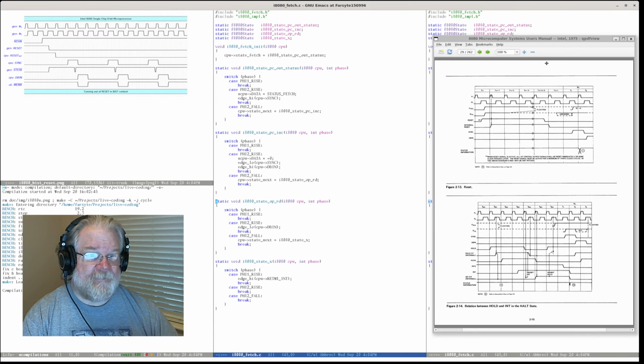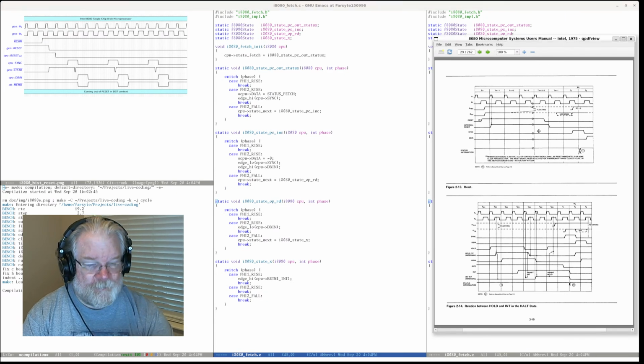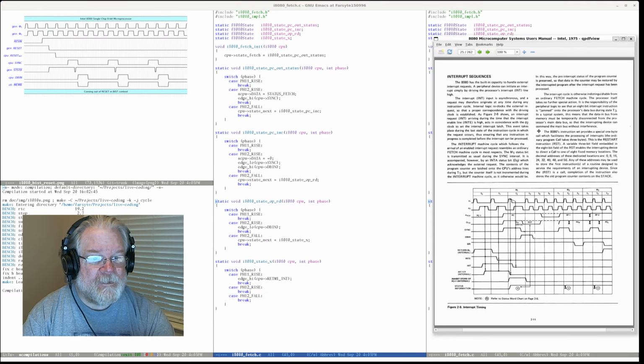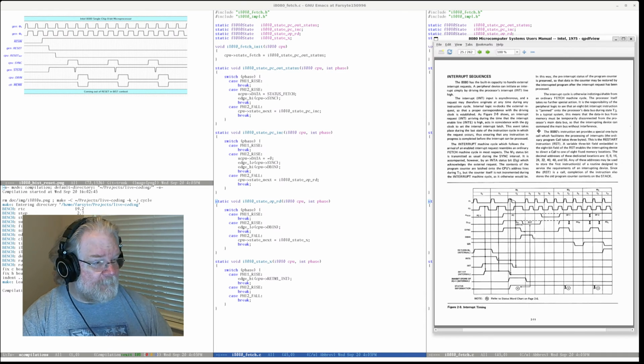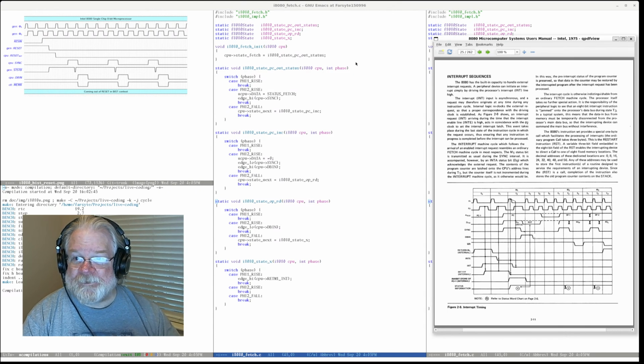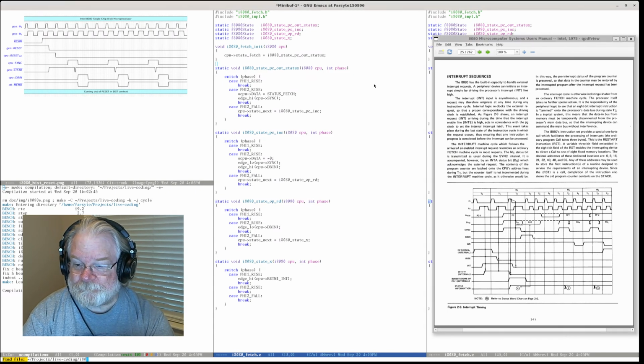Go back to i8080 fetch, and let's switch our window over to a typical instruction fetch cycle. So we've got a number of things that are happening here that we're not doing. So let's take a look. During T1, we should be driving our address from PC onto the address bus, along with driving our status and sync. But we're not doing that because we don't have one yet.